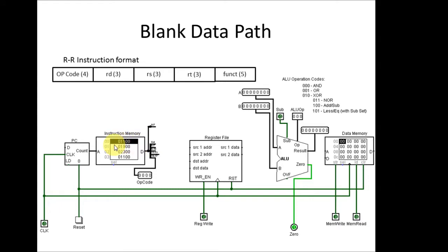This is read out, this is addressed by the program counter, so the program counter is 0, we're getting the first instruction, and this splitter here is breaking out each of these sections. The first 5 bits are broken out on this top splitter, the next 3 RT are in the next one down, then RS, then RD, and then finally the opcode here.